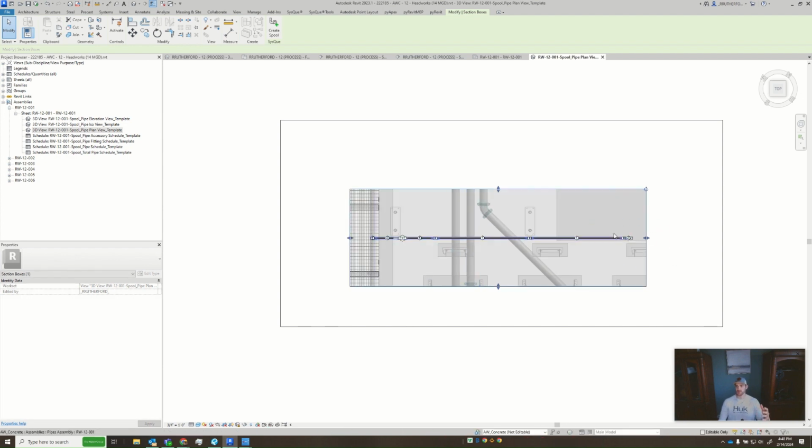And I also want to make sure that I have enough other elements, whether it's structural or mechanical, to dimension off of. I do not want to have an internal dimensioned pipe system. They're not going to be pulling pipe dimensions and tape on what they've previously laid out. Typically they want to pull off of a reference, so I will try to make sure that there is a decent reference available for them to make sure that they're within the same area.